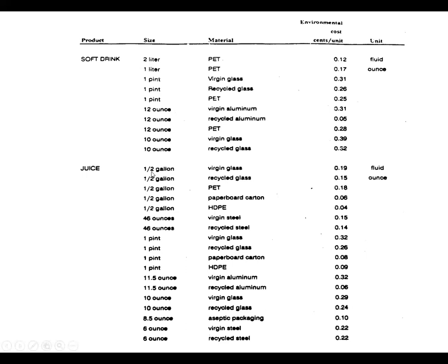Okay, but in that regard, making those decisions, do you buy the material in a PET container versus a glass container versus a recycled glass container? Okay. Now you will see this is cents per unit, okay, and these units are in volume here. But even though if we go back and look at the impacts of plastics versus, let's say, recycled glass, the amount of plastic to hold the same amount of liquid is a lot less than the amount of recycled glass to hold possibly the same amount of liquid. So if you look at these three things here, okay, PET comes in the best from an environmental impact because it's lightweight, it has much less material.